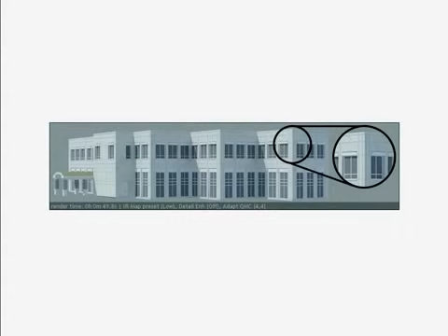So when should you use the adaptive QMC sampler? Well, this sampler really is best suited for scenes where a high level of detail is needed or there are a lot of blurry effects. And as a general rule, I would recommend using this sampler when your rendered image has up to 75% of its space requiring this kind of detail.